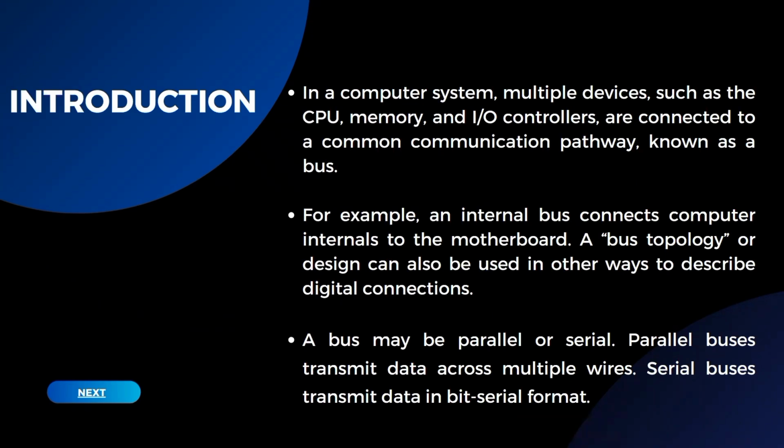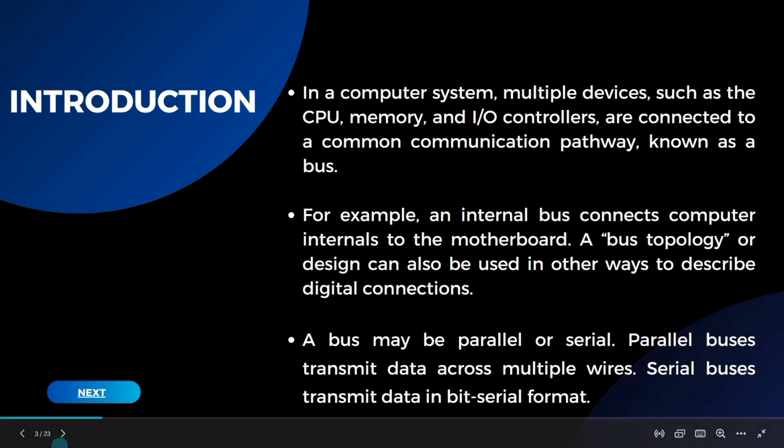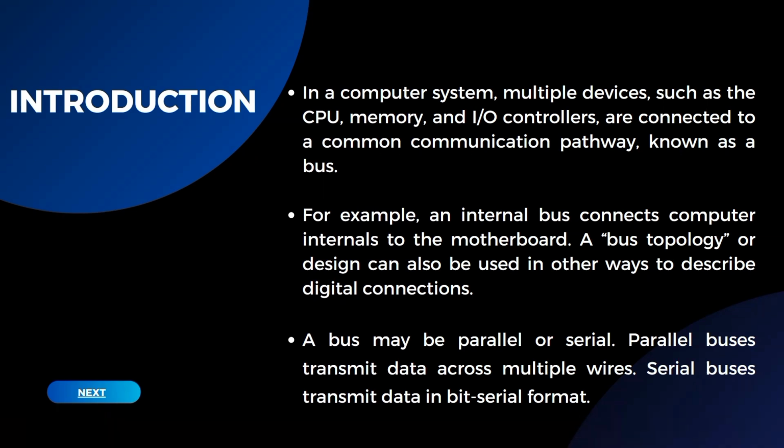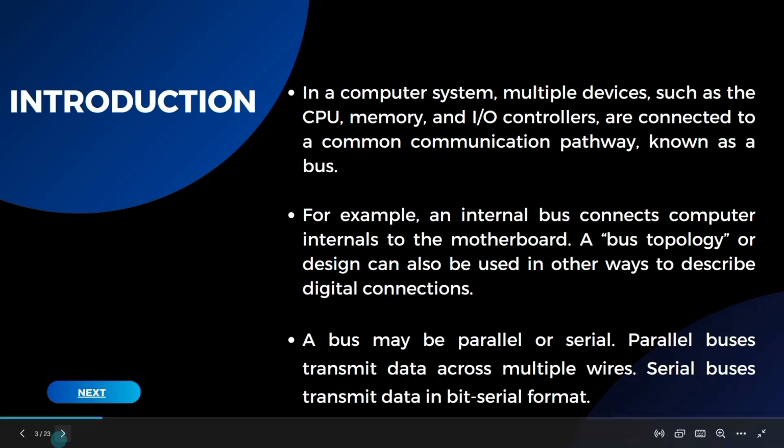Bus arbitration is the process of resolving conflicts that arise when multiple devices attempt to access the bus at the same time. When multiple devices try to use the bus simultaneously, it can lead to corruption and system instability. To prevent this, a bus arbitration mechanism is used to ensure that only one device has access to the bus at a given time. There are several types of bus arbitration methods, including centralized, decentralized, and distributed arbitration.